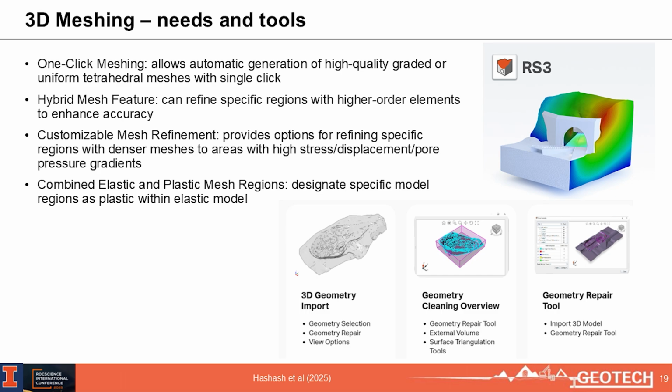And so you have to be able to import the geometry. You have to be able to clean up the geometry. And you have to be able to repair the geometry, make sure you don't have distorted elements or overlapping elements. It's a non-trivial exercise. And having a tool that is handy that will allow you to do that, I can tell you, I have spent lots of time when we didn't have as good tools to develop the meshes, but having these types of tools is making the development of complex SSI models feasible.